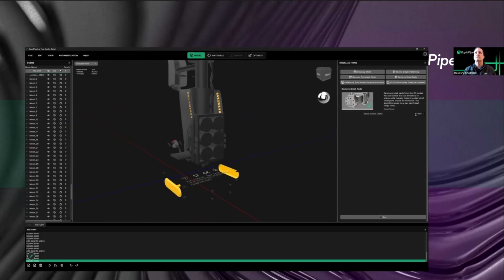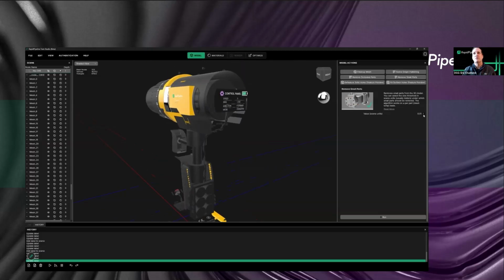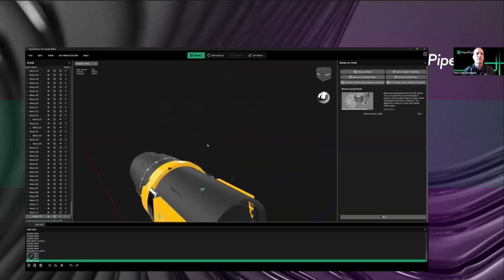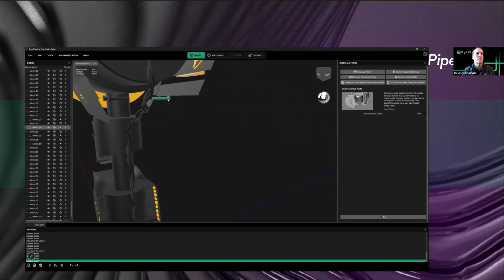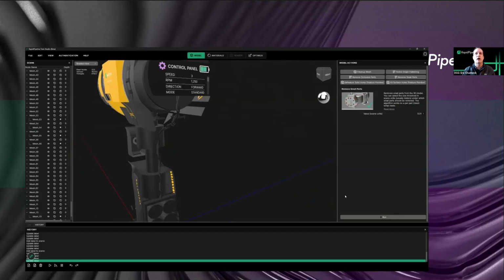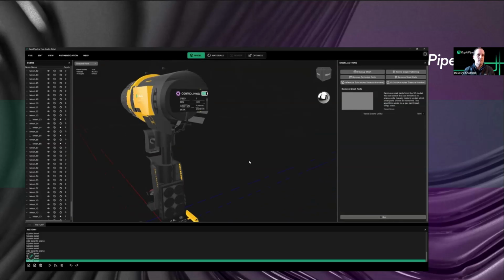What it does is it looks at, in scene units, how small parts should be to remove. By default, scene units are in meters. So this value is saying anything that's under a centimeter for the largest dimension of its bounding box. If we look at a screw, for example, one of the longer ones, and the longest dimension of its bounding box is under a centimeter, then it'll be removed. So let's just try it. Let's run it and see what happens.